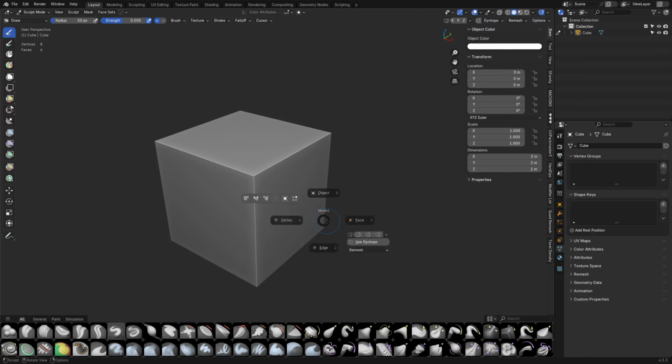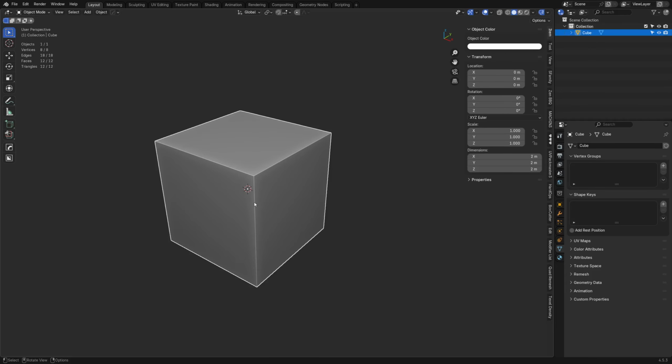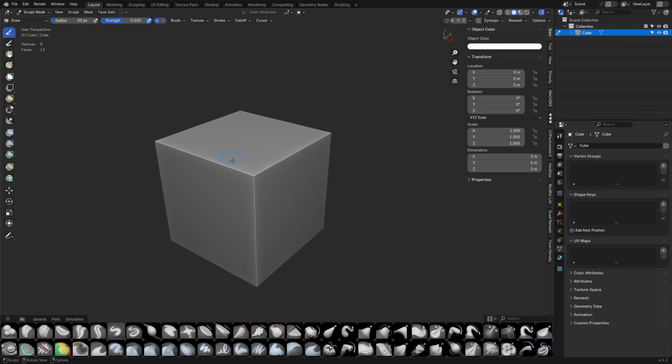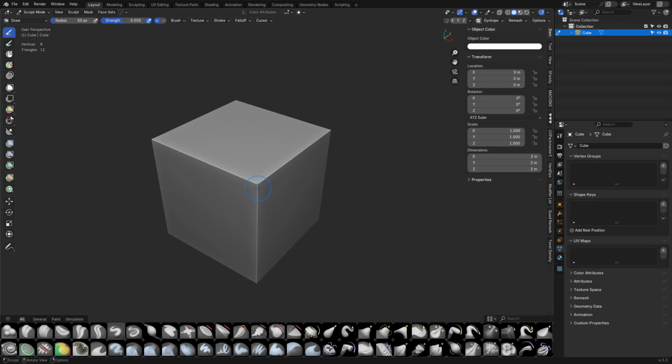And it's only complaining if we go back to object mode and grab our cube. We can remove the UV map right here. Tilde key back or tab key back into sculpt mode. And you'll see next time we turn on dynamic topology, it doesn't complain. That's all it's saying is that it's got UV map information. All right, so with that out of the way,